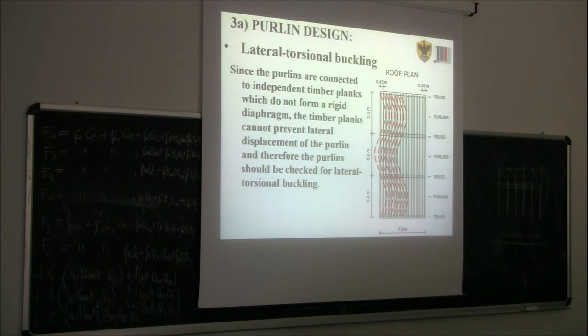However, in our case, they are inclined, the two floors are inclined. Here we have two, you have something like this. So we need to ask ourselves, if here I connect, those are the purlins, and here I have my joist, are those purlins able to prevent this buckling, this movement of the purlins in this way? Well, this one, to buckle here, it should lift up also the other pitch of the roof, because they are not in the same plane.